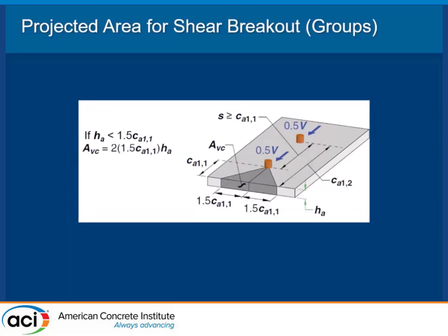And we have three different modes here, so you have to look at how your base plate or your anchor system sits on top of whatever element that you have. A lot of times when you have a base plate with oversized holes, if the oversized holes are just minimal and there'll be minor deformations, you can assume that half of that load will go into the front anchors, the anchors closest to the edge, and the other half will go in the back.